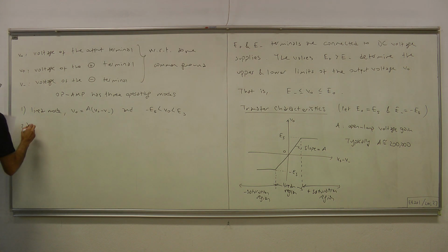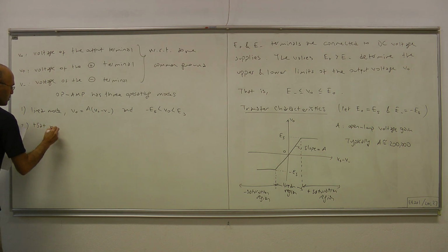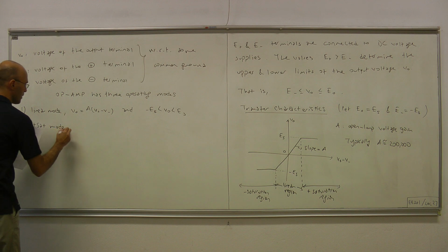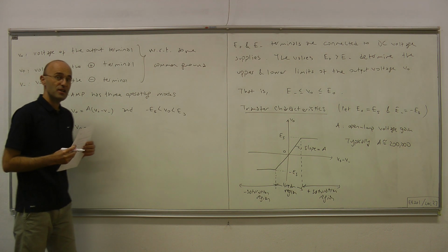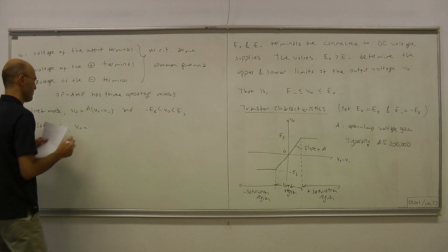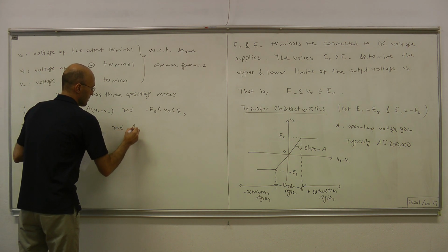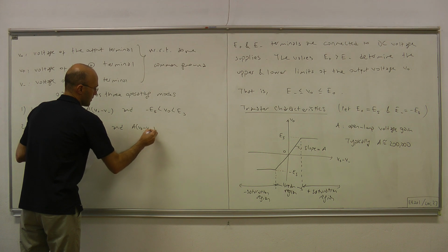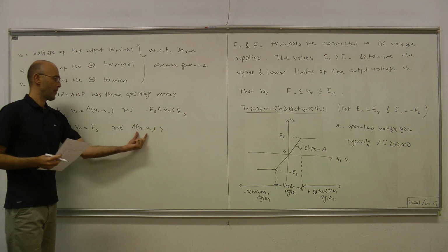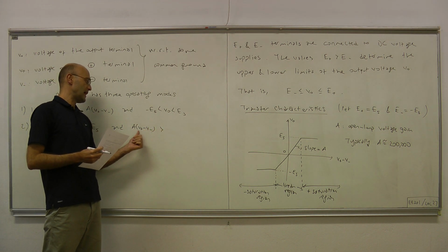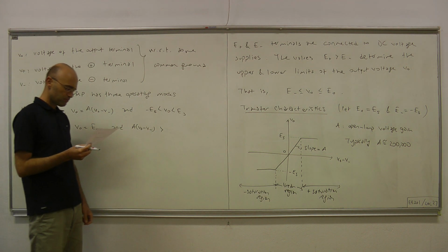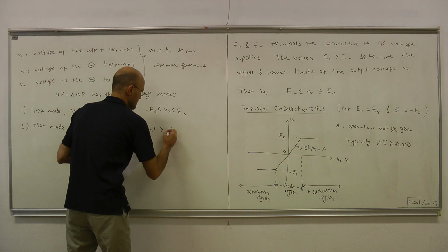We have the positive saturation mode, where V out is fixed at positive saturation voltage, E_S, and this product of gain and voltage difference is larger than E_S. Okay.